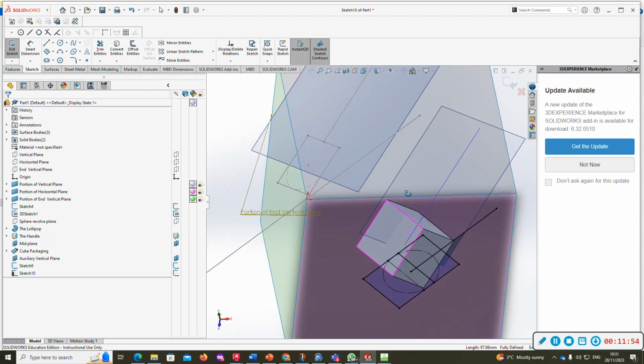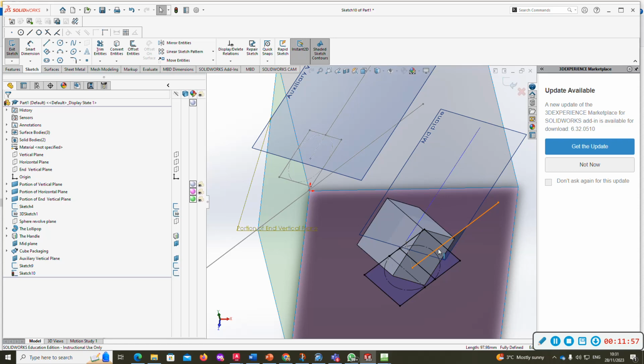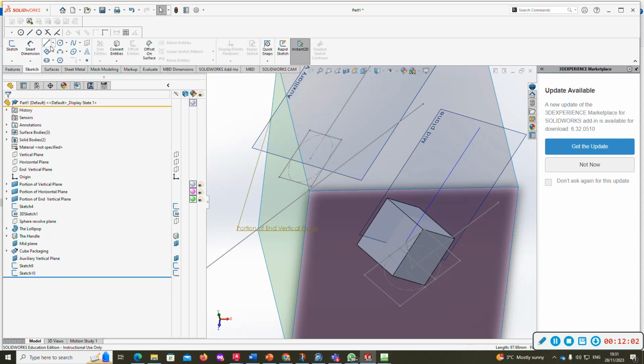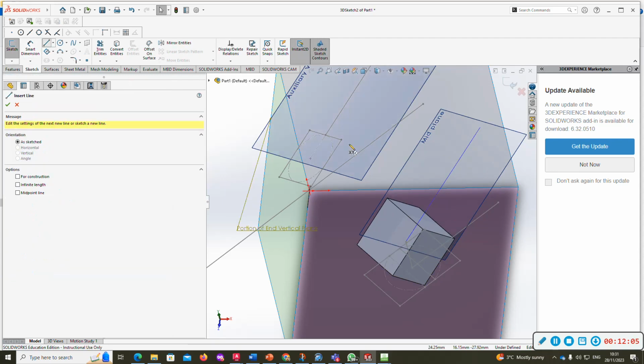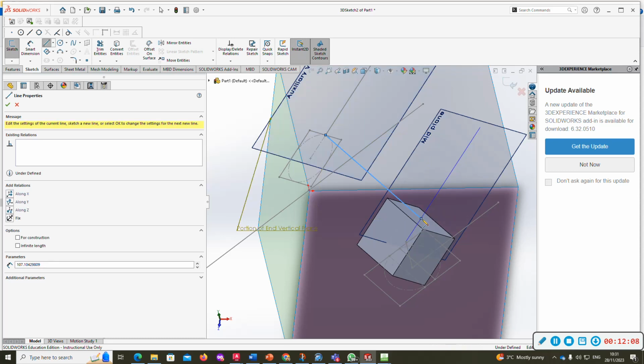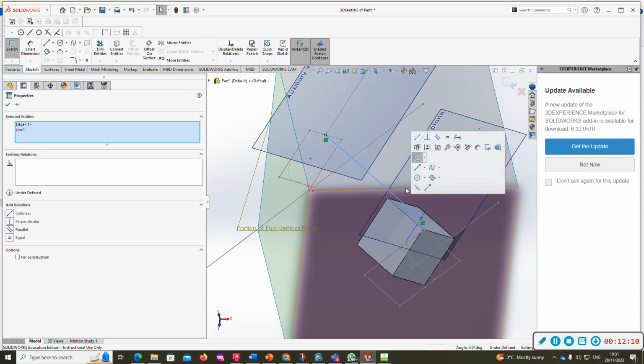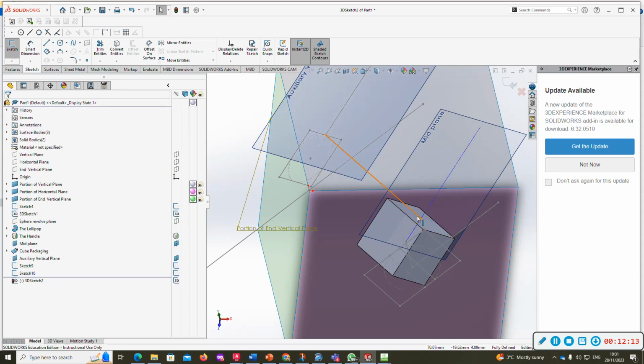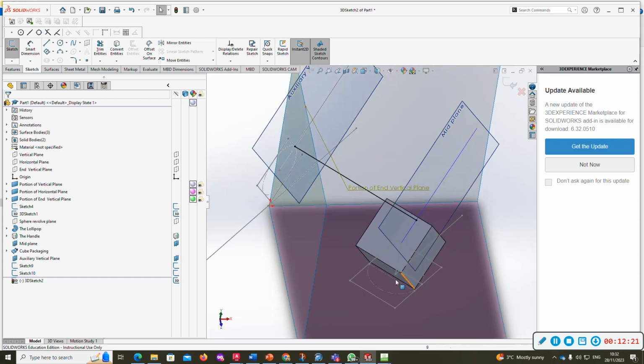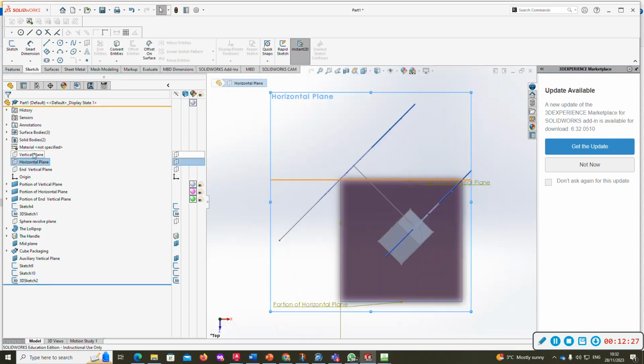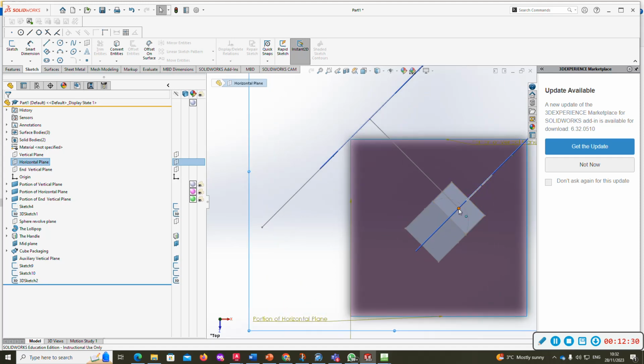The question is on our drawing, how do we figure out when that becomes hidden detail? Well, the solution will lie in a 3D sketch here. Line, I'm going to bring the line back to here, and click the line, hold control, click that one, make parallel. See the way it's gone black now. So if you project back from your auxiliary elevation, this locates the moment in plan view that it becomes heavy and hidden. So that's the location for what's heavy and what's hidden.